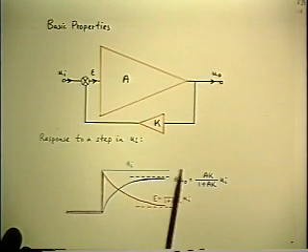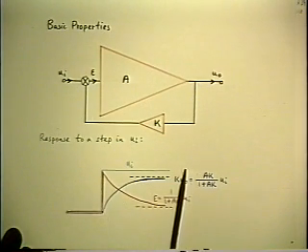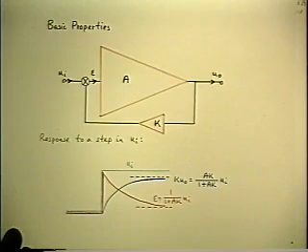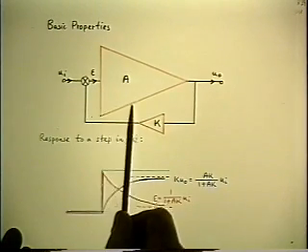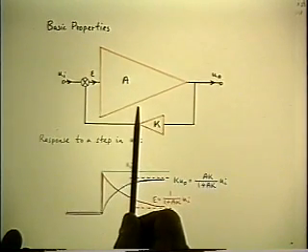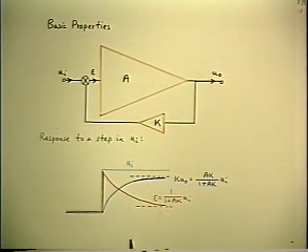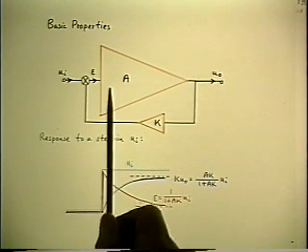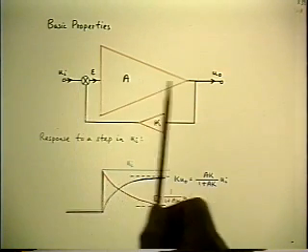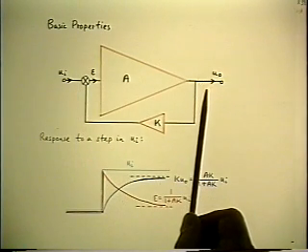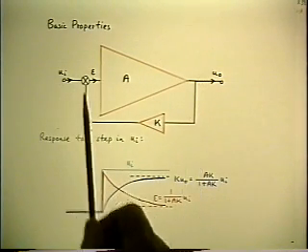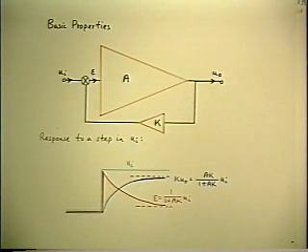That's the green line. What does the system do? Well, first, every practical system has finite bandwidth, which if you translate that into the time domain means that it does not respond instantaneously to a change of input. Therefore, since before the step arrived, the output was 0, then immediately after the step arrives, the output is still 0.